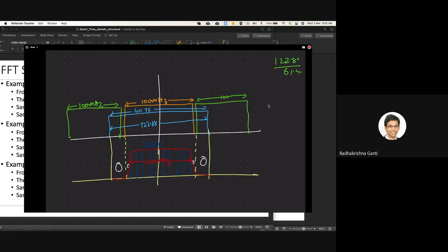On the reception side, you are going to get junk from this guy, and from this guy, and from this guy. So you take an FFT of whatever, 4096. Then what are you going to do? You know that your subcarriers are only 3276. You discard all these edge subcarriers and consider only 3276 subcarriers. Therefore, there's no interference from here to here.